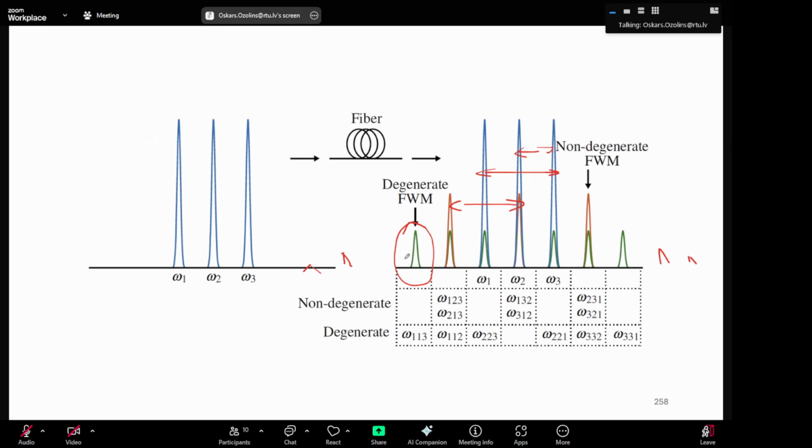So with coherent systems, you have a lot of freedom so that you can get better signal quality, better, higher capacity, but it comes at a price. Like we were talking about, from OOK to PAM4, the signal to noise ratio, the eye opening, drops like 3 times. So in this case, when you put more channels and you put quite high power, then nonlinear effect starts to limit how many, or at all, you can transmit the data on these channels.